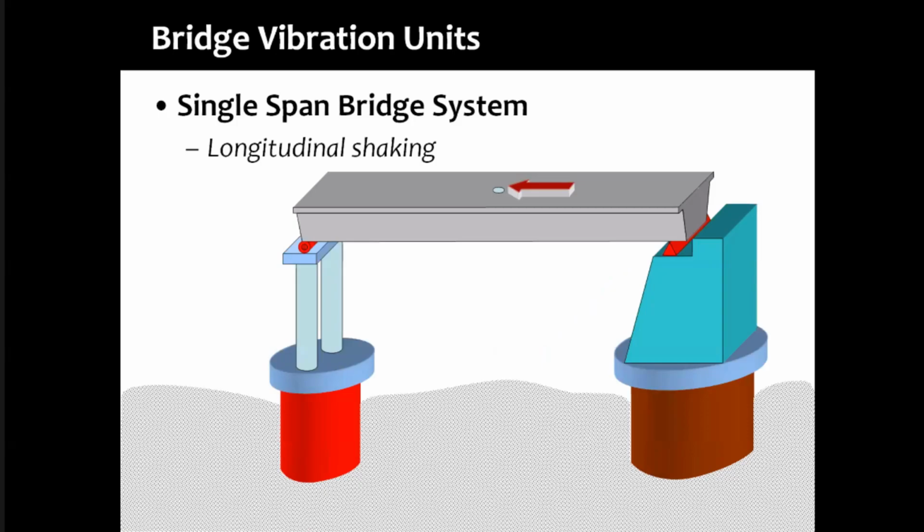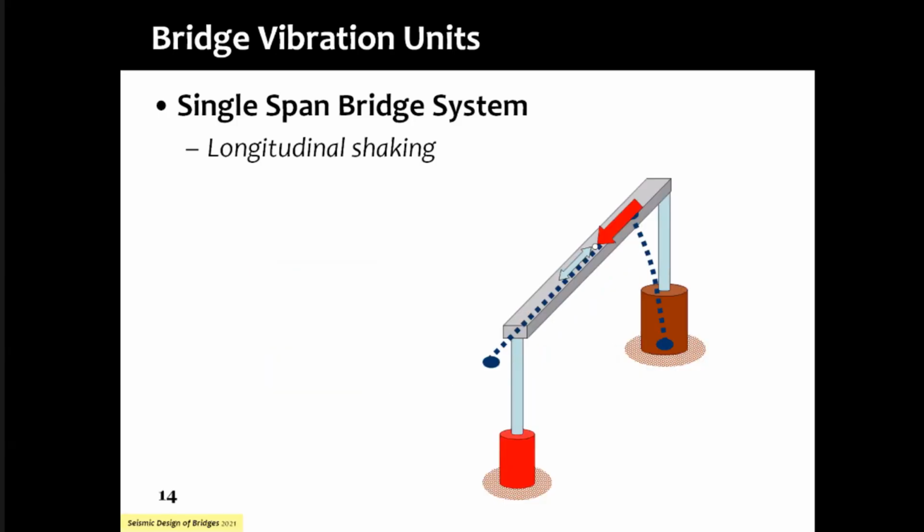But if you look at the longitudinal direction, only one side set will act together. This is very important to understand, where will the inertia force get transferred. In fact, as a designer, you will have the freedom to decide where the inertia force should get transferred. It's not like a black box computer program. Our students tell us, sir, this is the correct answer, the computer gave this answer. That is not what we want to accept as designers.